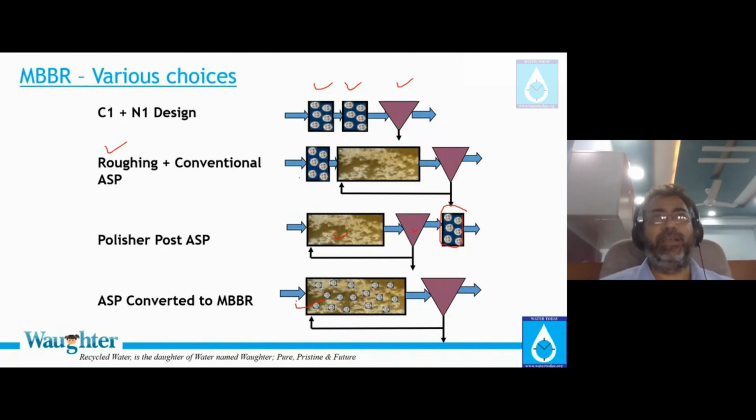But believe me, I'll repeat the word again many times. Is the microbiology different? No. Same heterotroph, same autotroph. Only this time they are attached growth, and beautiful attached growth. The growth is attached, but the entire carrier is traveling here and there, like in a conventional activated sludge process. So MBBR, in terms of the microbiology, understand my word, in terms of the microbiology, is much more superior than MBR. Why? Because it encourages colony groupism and culture of the bug behavior.